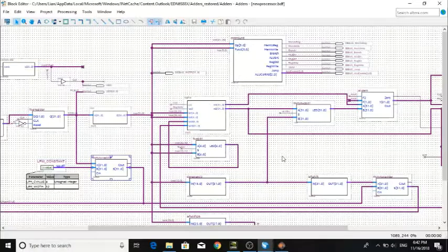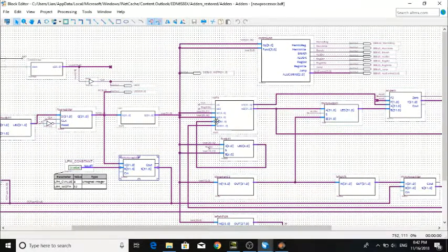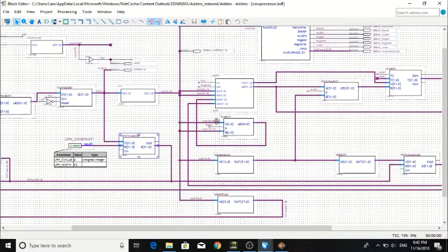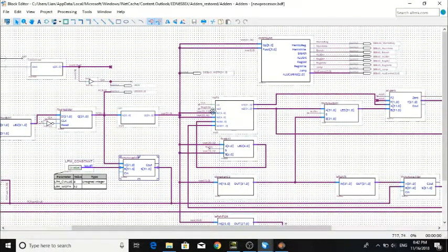Jump uses a label which the hardware does not understand. When the program is assembled, the jump must be converted into a memory address. That memory address is then understandable by the hardware, thus allowing the hardware to perform the jump instruction. Jump, like all other instructions, is fetched into the instruction memory from the program counter, which is here. It is also fetched into the adder where it's incremented by 4, which is here.